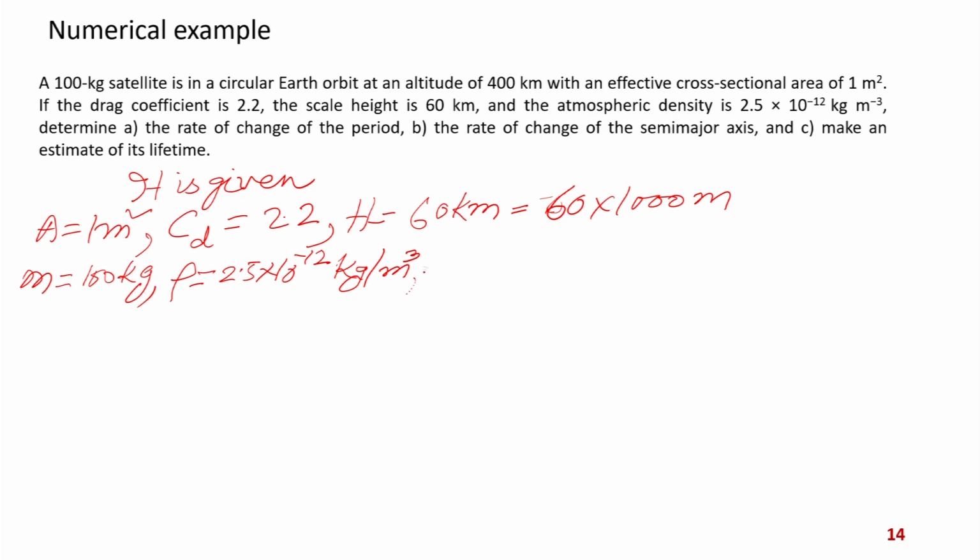and the altitude A is equal to. So, it is given from the surface of the earth, so you need to add the radius of the earth. So, A will be equal to 400 plus the radius of earth is 6378 and these units are in kilometers, so you need to multiply by 1000, then it will be in meter.